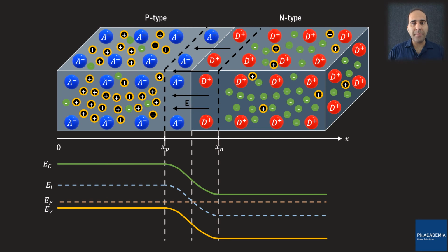As you remember, in one of the previous lectures, I was discussing the side-by-side energy band diagrams of the P and N type semiconductors. I have them drawn here one more time. What I did not talk about was the shape of the energy band diagram in the depletion region. It's now time to discuss it. In the depletion region, the energy levels EC, EV, and Ei bend. However, EF remains intact. In equilibrium, the Fermi level EF is a constant and therefore can be taken as a reference energy to draw other energy levels.